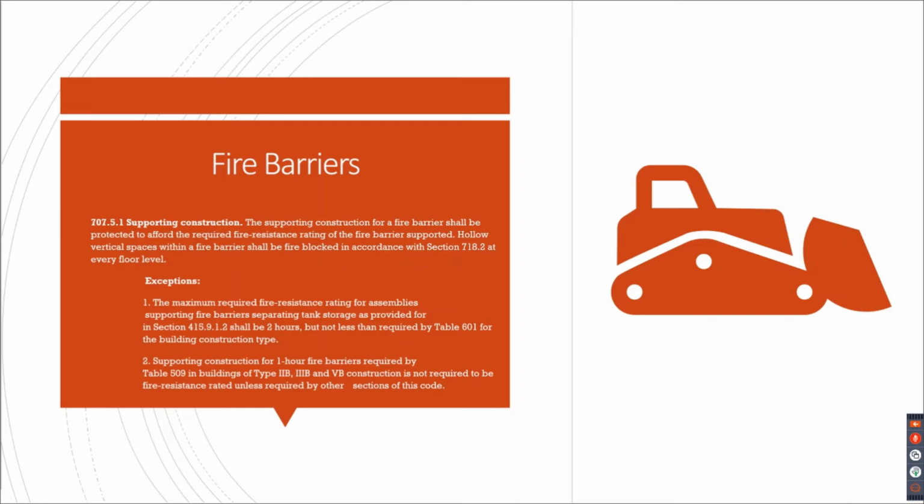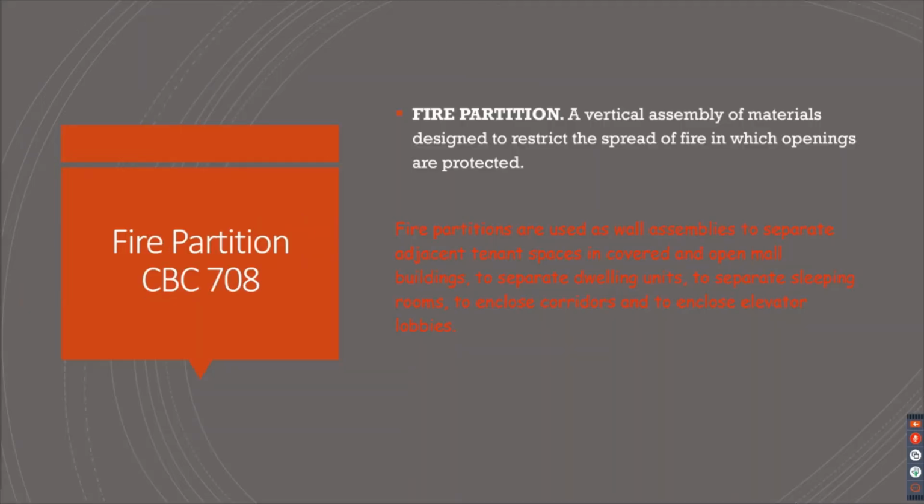If you've got a 2-hour fire barrier on a floor that's only required to be 1 hour, that floor is not rated the same as that wall, and that supporting construction needs that same rating. So anyhow, this section talks about that, and there are some exceptions to that for different construction types.